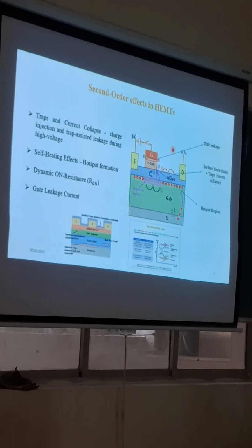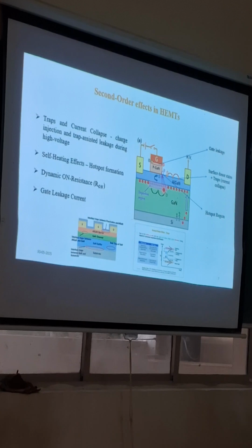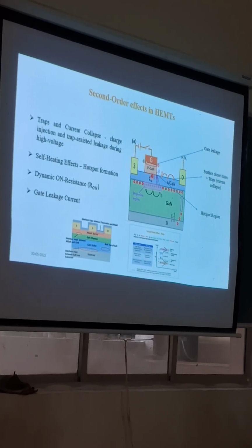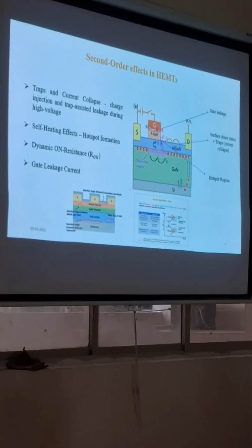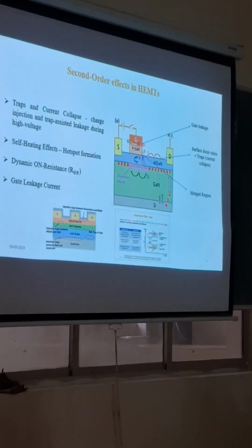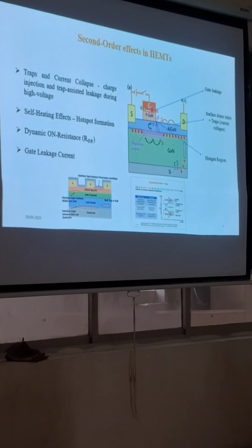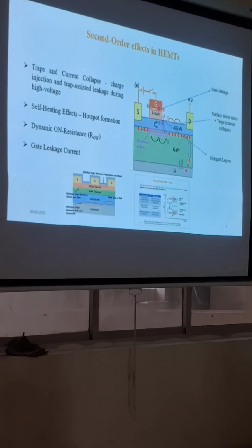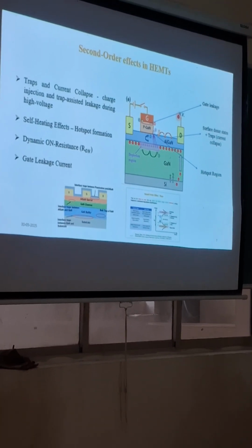Here we see the gate loses stability due to electrons which pass through the GaN and get into the gate metal. Normally the Schottky diode would form, but at some high voltages the electrons in the channel leak through the PN and get into the gate electrode. That hurts the gate reliability, so that should be mitigated.